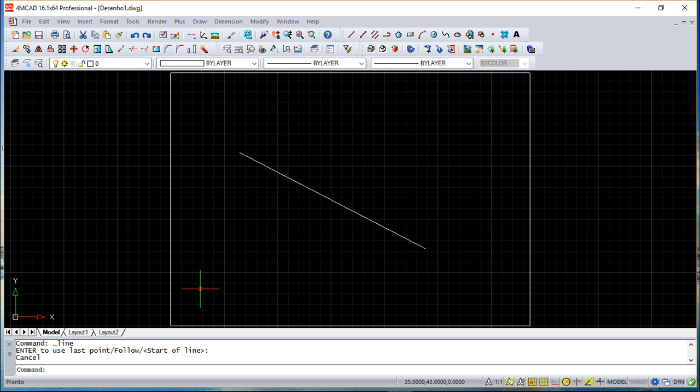Instead of absolute Cartesian coordinates, we can work with relative Cartesian coordinates, which is basically the same. Let me write down here 10, 20. This is the absolute one, but I can use another format, which is with this symbol, the at sign, and then using the same notation.